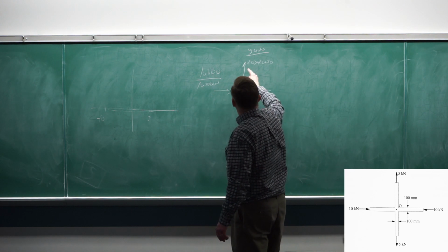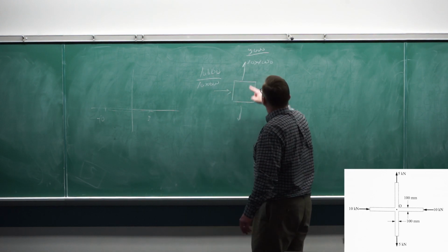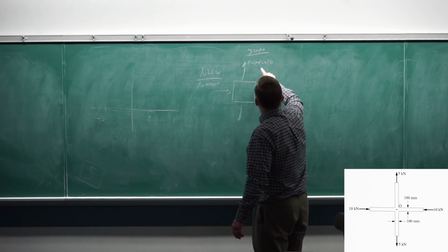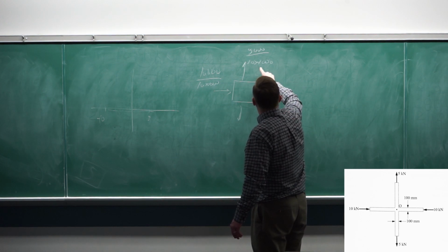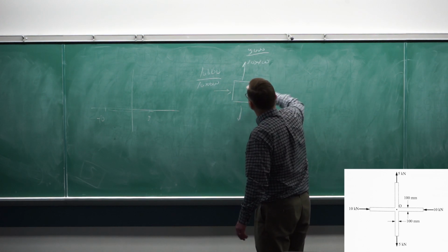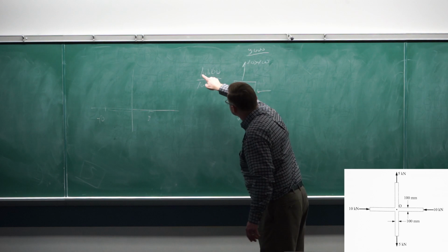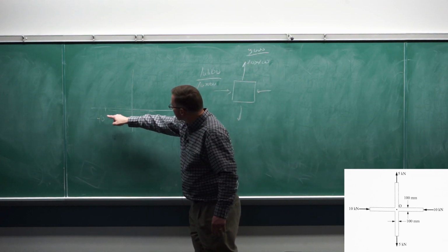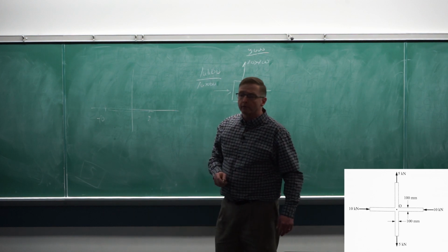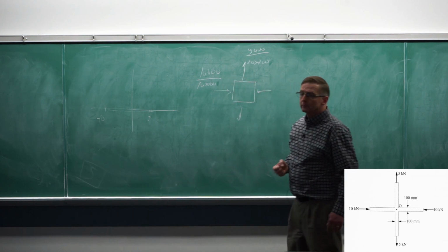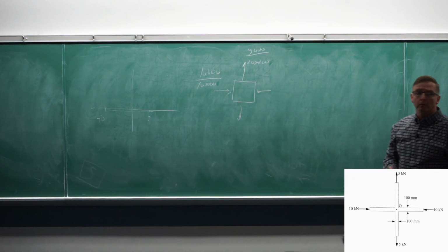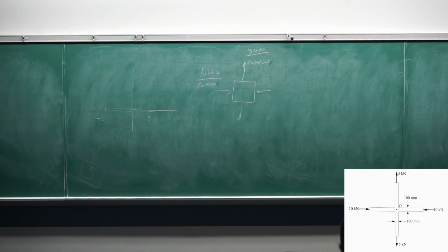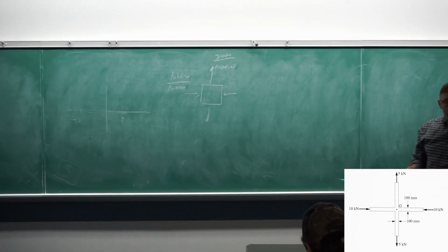That's 10 by 100, right, not 10 by 1,000. That gets you a stress of 10 and a stress of 5, and you're still back to Mohr's circle with diameter 15 and radius 7.5. So that's a pretty clever problem. If you really understand the biaxial state of stress and the resulting Mohr's circle, you can do that in a minute.